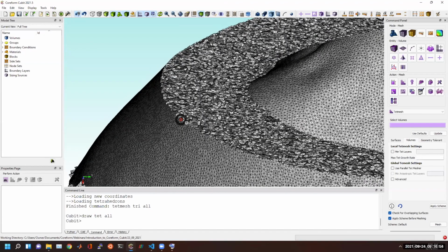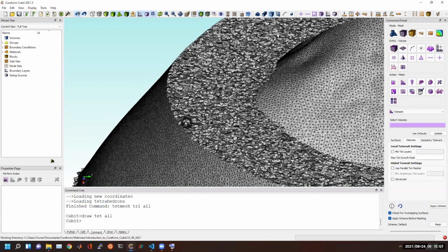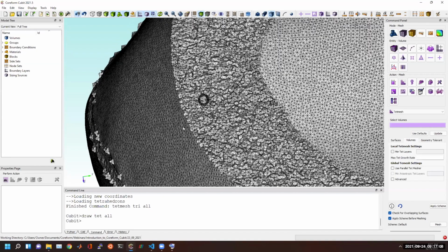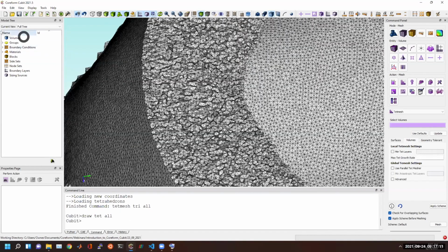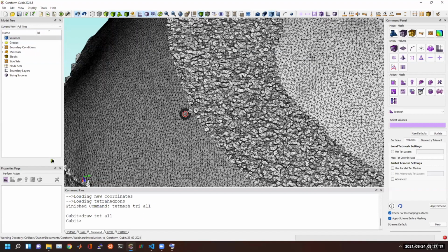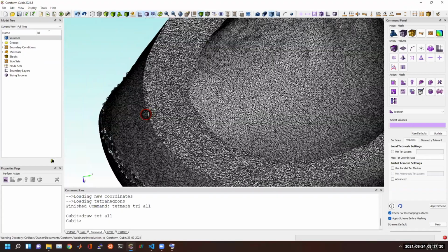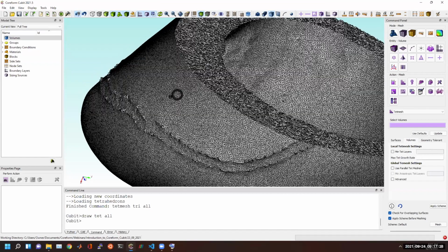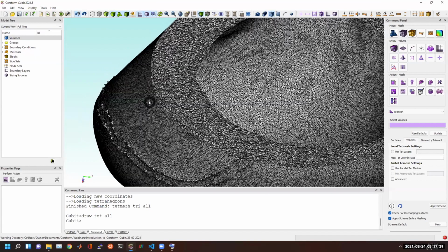By disassociating, we've removed this extra geometry that we don't want to muddy the simulation or the models that we're trying to build a mesh for. So in cases where the geometry is just too heavy for what you're trying to do, you can disassociate, and that allows you to clear out geometry from your model and just work with the triangulations. We find that sometimes preferable for certain kinds of models, like this heart, where you're not really going to care about that input geometry. But I will show why you might care about that input geometry in a little bit.